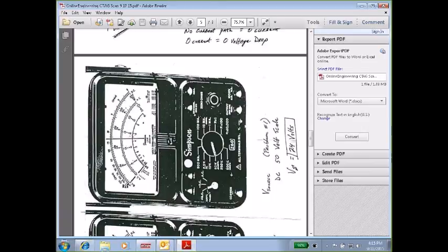if we look at this one, where that needle is at, it's one little tick mark shy of being exactly halfway, which would be 25 volts. So one tick mark shy of that is 24 volts. Now, because it's on the 50 volt scale, that does not mean take that number and multiply it by 50. All that 50 volt scale is telling you is the maximum voltage you can read on that scale. If you want to read above 50 volts, you've got to go up to the next scale.